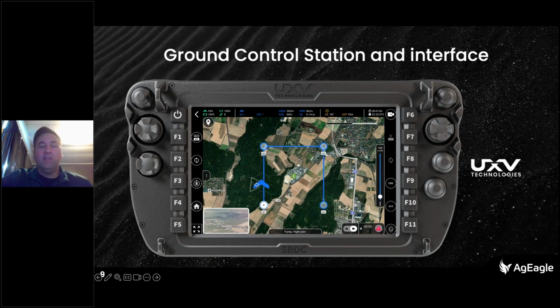So the entire left side is going to be all of the aircraft inputs itself, and the entire right side will be anything that you need to do to adjust the sensor while in flight. You can plan custom flight plans. You can do point out and back type missions. You can set up boxes around NAIs. Another thing that's great about this too is it has lat-long integration and MGRS.